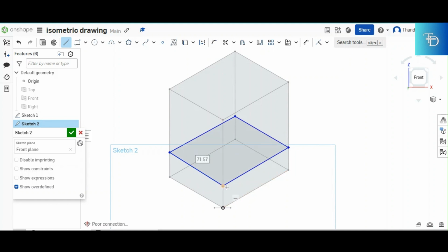Since you've marked 25 here, you only mark it once. And then you take your what? Your 30-degree ruler. You transfer the point up to that corner. You transfer it to the next corner. You transfer it to the next corner. And then it comes back where it started.